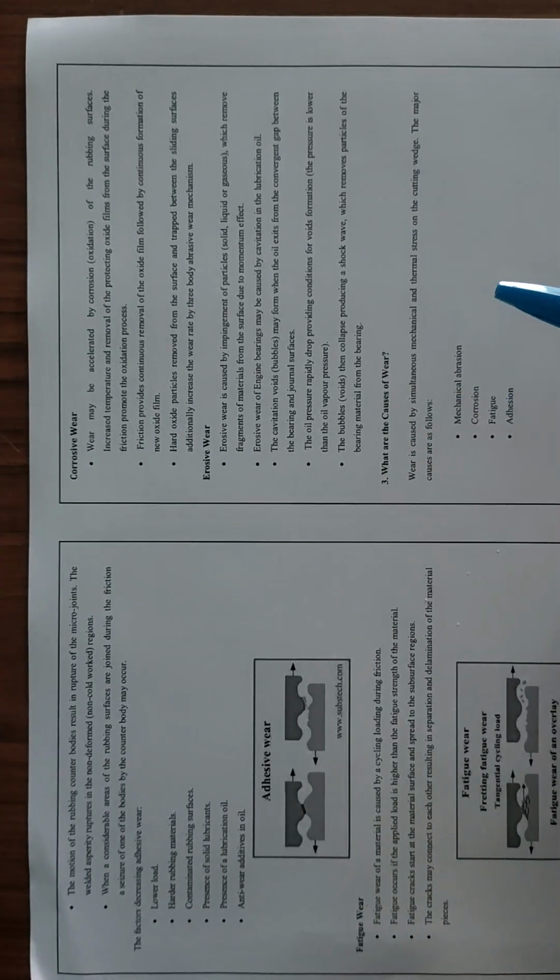What are the causes for wear? Wear is caused by simultaneous mechanical and thermal stress on the cutting wedge. The major causes are as follows: mechanical abrasion, corrosion, fatigue, adhesion.